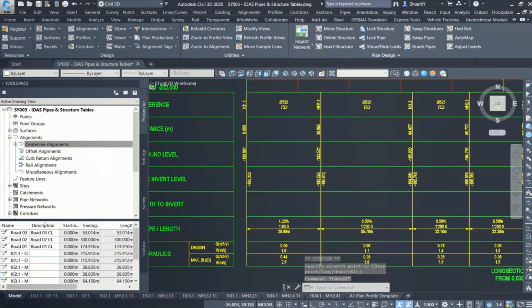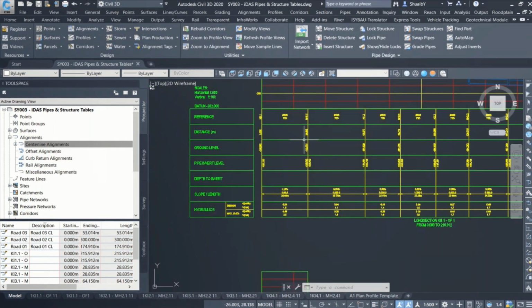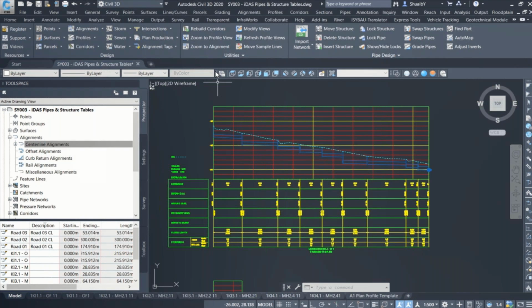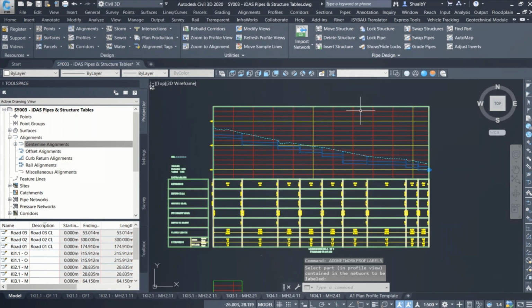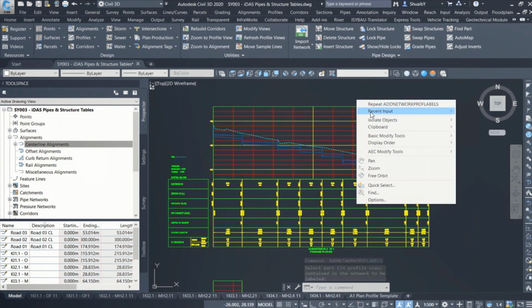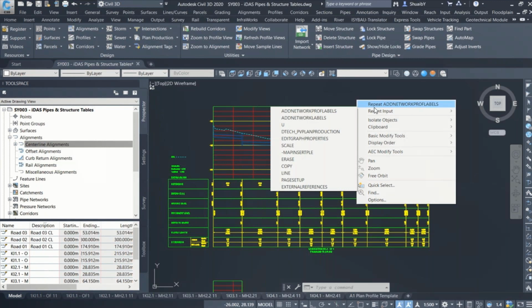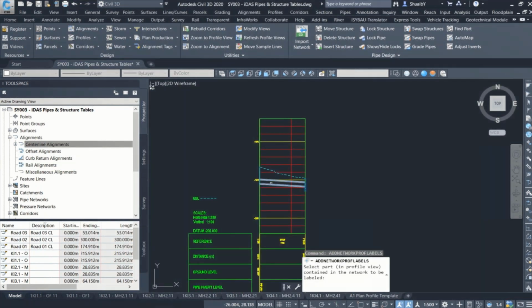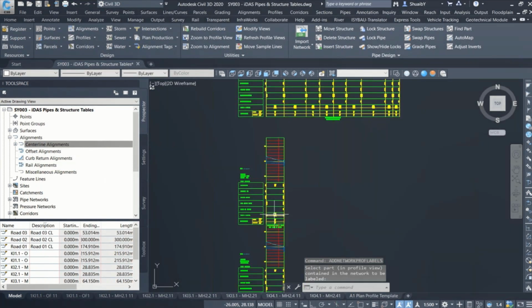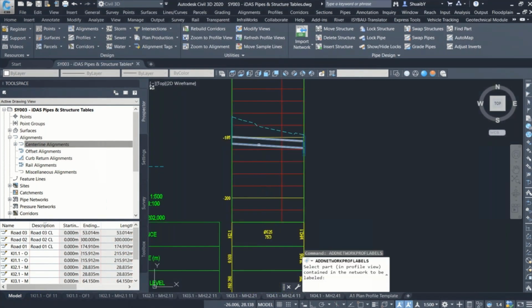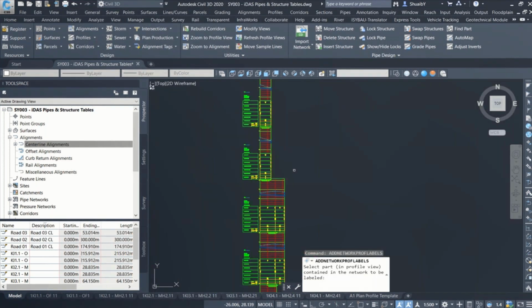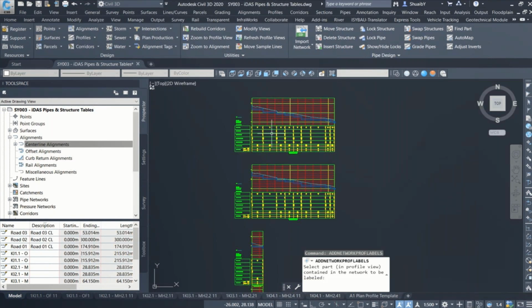You will have to go and click at each pipe network or each profile network. This is quite easy. It's very straightforward. Again, all you got to do is just click on the pipe and it'll add it. So I'm just using the quick repeat function because that's the last command I've used. Again, you can see your AutoCAD grounding comes in here quite a bit. So if you're a person that loves your AutoCAD shortcuts and stuff like that, with Civil 3D you would really enjoy it. So yeah, I'm just going to add it for a few more.